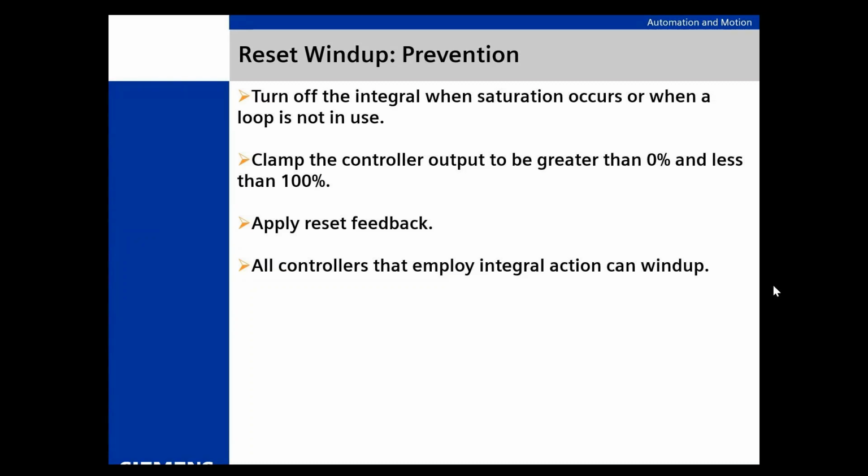So it'll wind up. And you see that not as much as you used to, but you do still see it. And it says, like at the bottom, all controllers that employ an integral action can wind up. That's true. Now, steps have been taken over the years to stop that or slow that down, and they have, but it can never really eliminate it. So it's always there. It's always a possibility. All right.